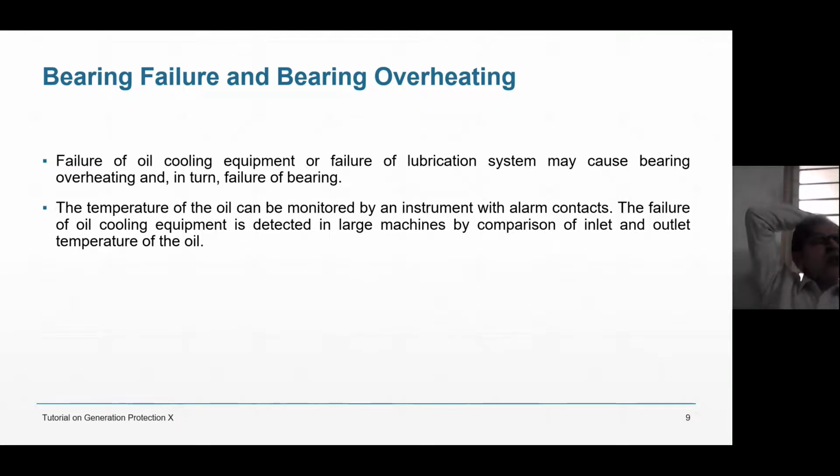I was told that the cost of the thrust bearing is somewhere around 20 lakhs, and cooling of the thrust bearing is very particular. I mean, it is a very complex arrangement. It has to be cooled by oil. There will be an oil seal also, because hydrogen should not come out.